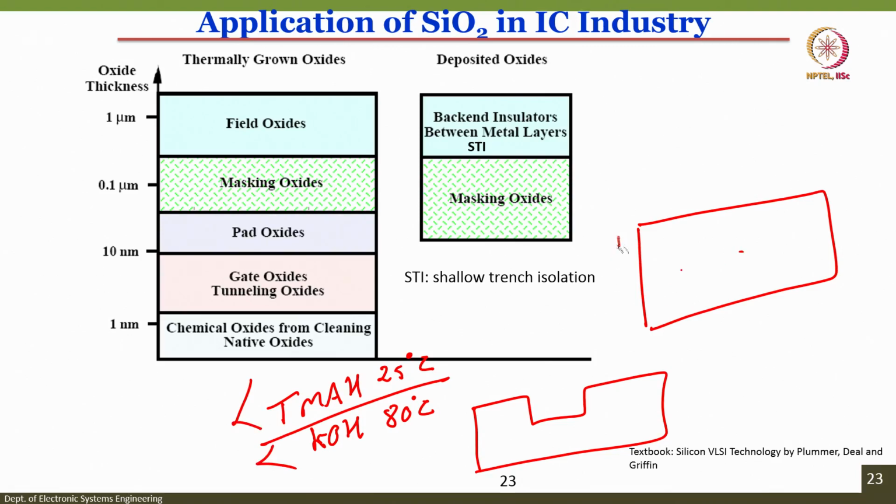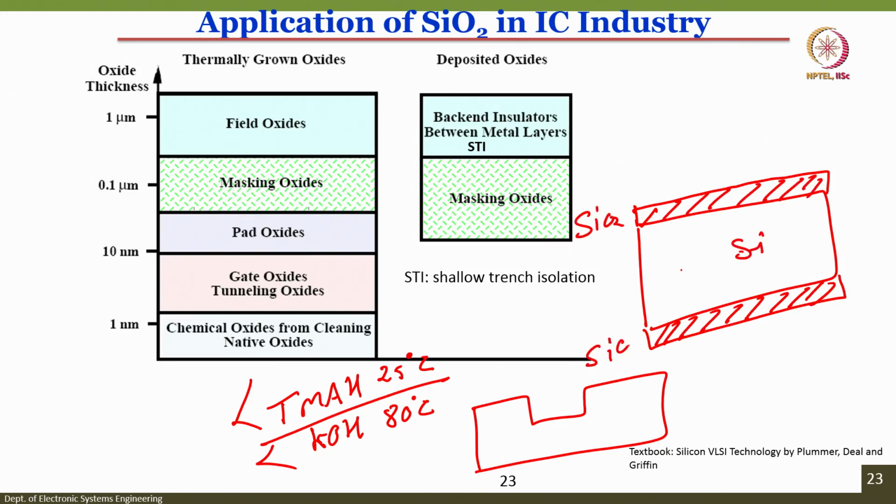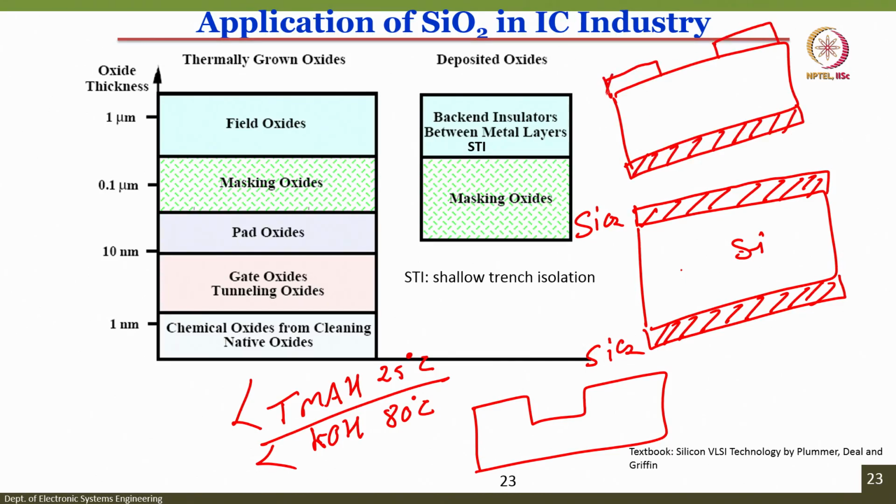So, what you use is a masking oxide. That means you deposit or grow silicon dioxide onto the silicon wafer, and perform photolithography. When you perform photolithography, you save the silicon dioxide on the back side, and in front you protect the silicon dioxide in this region, and here you can see that this area of the wafer is exposed, right, this area of the wafer is exposed.